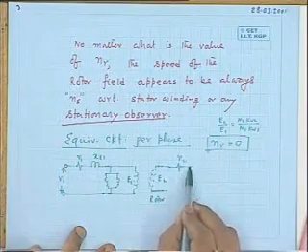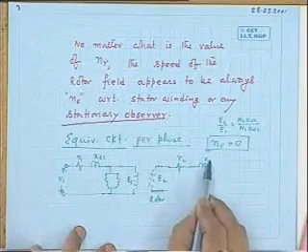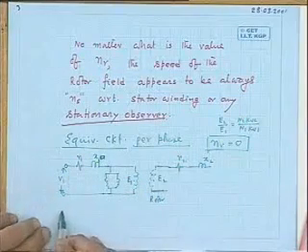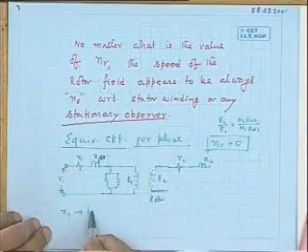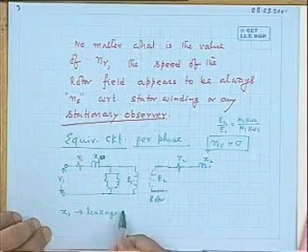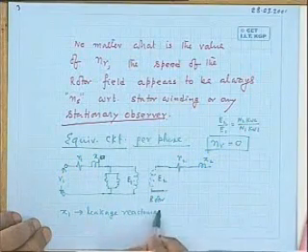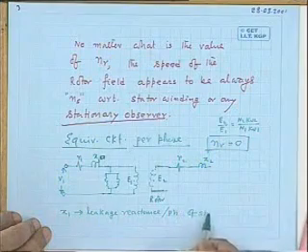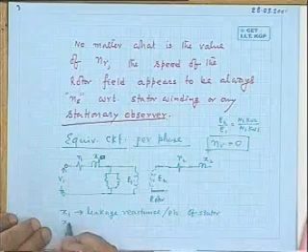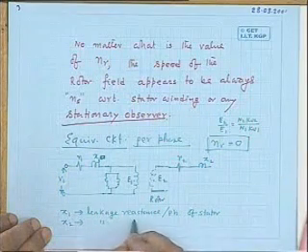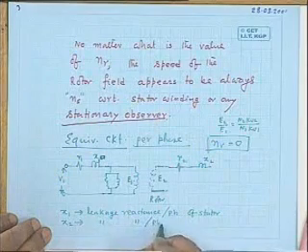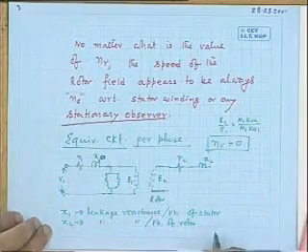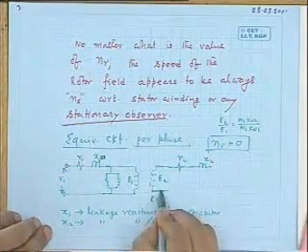Induced voltage, and you have shorted, no external impedance is there. So here what will come? Some R2 will come and a rotor leakage reactance will come. Instead of L I will write simply X1. X1 is the leakage reactance per phase of stator. And X2 is the leakage reactance per phase of rotor, and something else also I have to write, that I will tell.